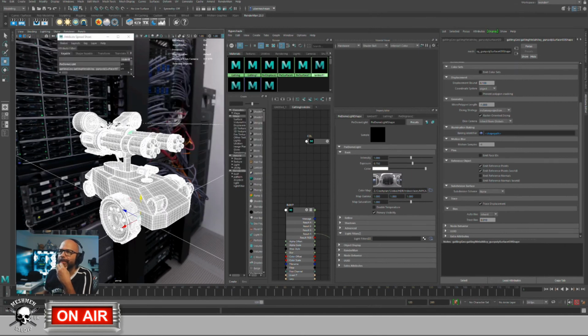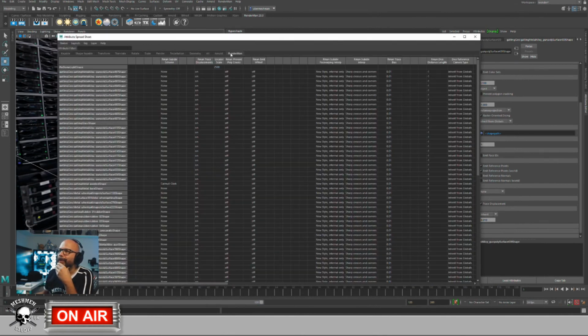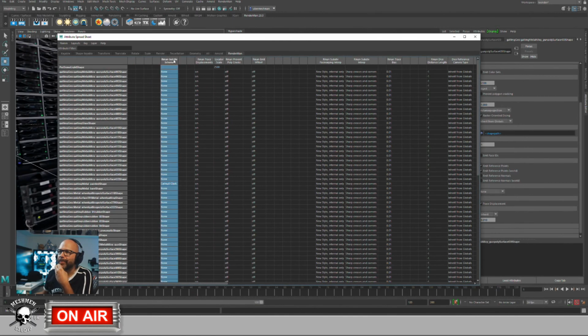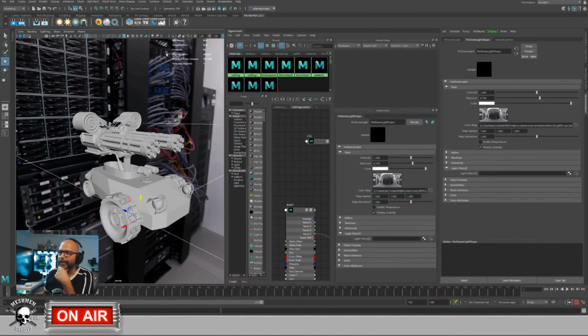There you go. Renderman, and go to Renderman subgroup scheme and set this to, let me see, is it 1, Catmull Clark? I'm gonna get Catmull Clark on all my selected objects. And let's see here. There we go. Let's go and set this to Renderman viewport again.